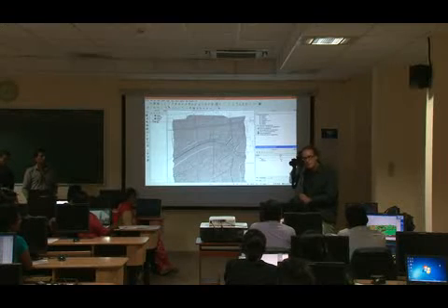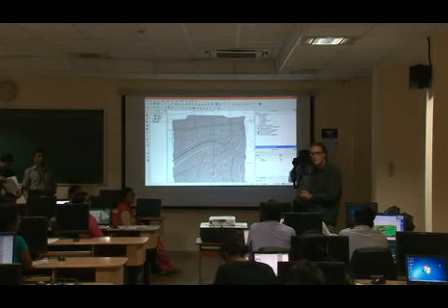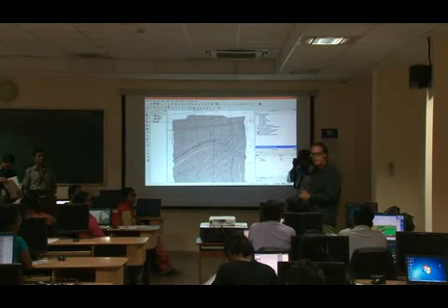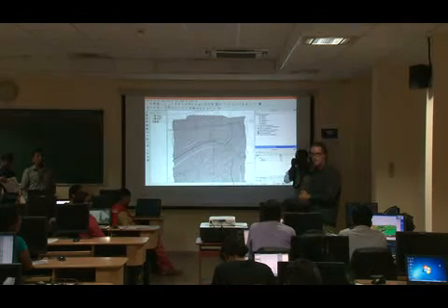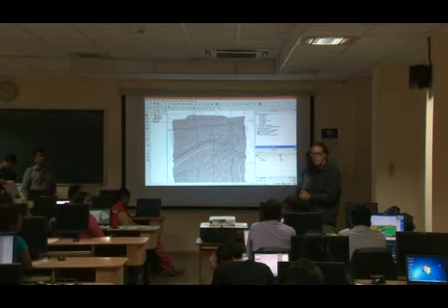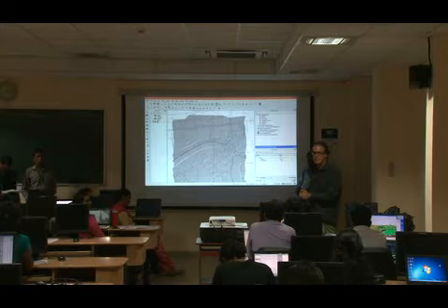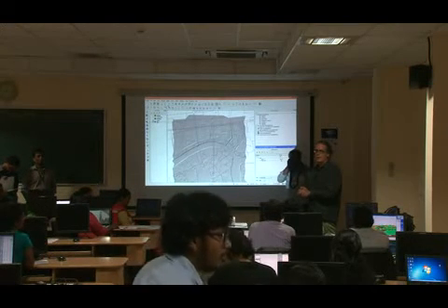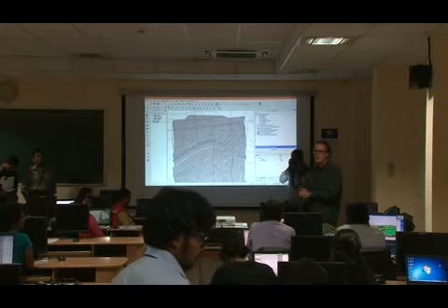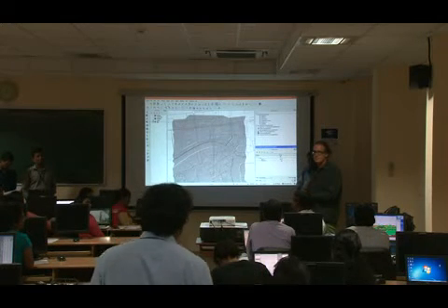My question is, like in DGPS we fix one ground station and the other GPS is on the platform, and it goes into a certain area, say a 10 km by 10 km area. Where shall we place the base station? Within the 10 km by 10 km area where we are going to acquire data, or if it is outside, how far can we keep it to not compromise the quality?